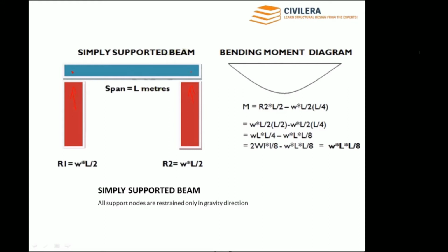So that is not pinned. When you are left alone, when no one is holding, and when you are moving your palm joint, then you won't feel any force, no pain. So that is a pin condition. You are simply supported. Here, that is the condition. Your slab cannot come down, but it can move in all other directions. So that is simply supported, and it will bend in this manner.